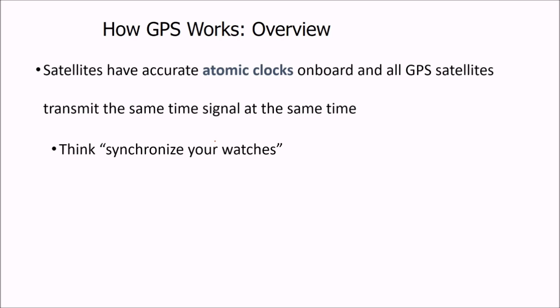So he can lock on to these 4 satellites, and with the technique of trilateration, they give you the exact position where you are. It varies. There are various possibilities because of PDOP and a number of inaccuracies. So you may get an accuracy of 10 to 20 meters, but there are also ways, real time or post processing, that you can get the exact location to sub-centimeter accuracy.